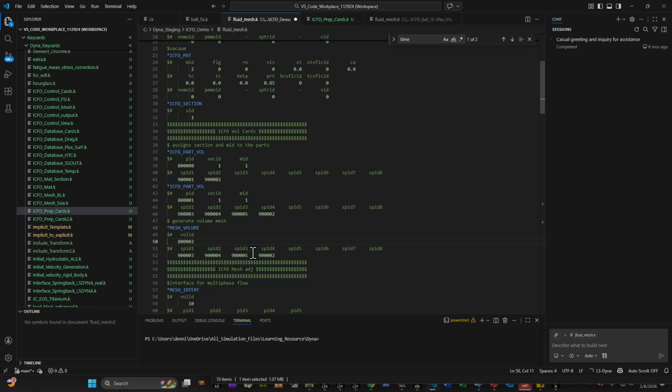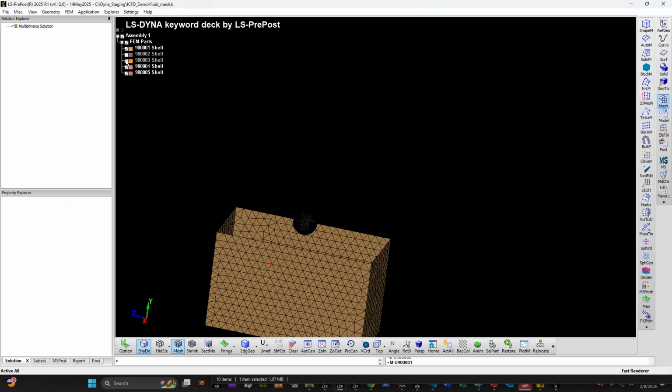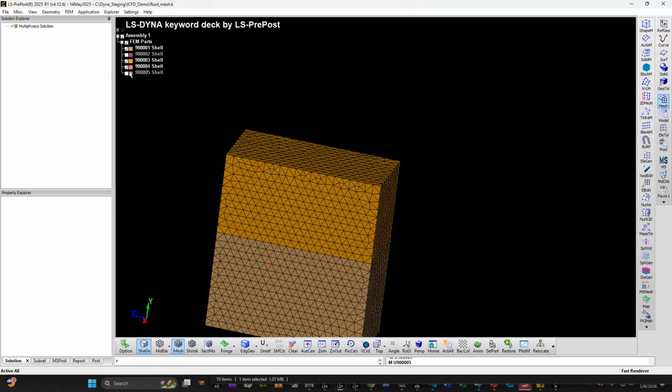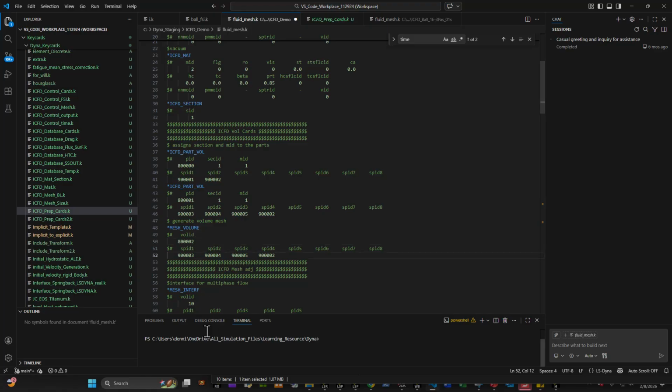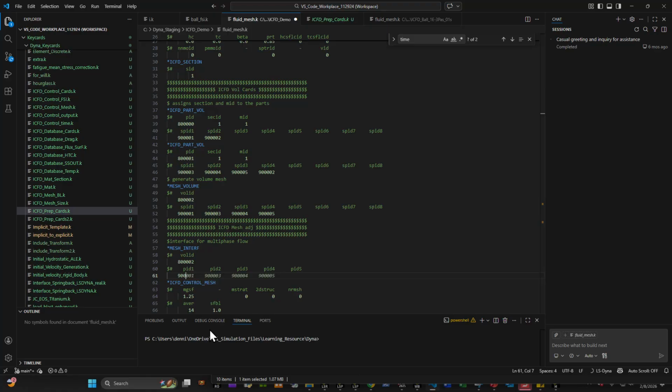Now the mesh volume is going to include everything except for 9001, right? So 9002 is going to be the interface. So the total mesh volume is going to include basically everything. This, and this. So these are all the bodies that you're going to include, which are the two balls and the surfaces on the outside, which are 1, 3, 4, and 5. Now, what we didn't include is the interface, right? Therefore, the interface has to go here. So I have to call the mesh ID and then add the interface here, which is 9001.